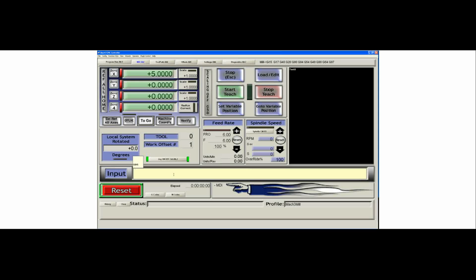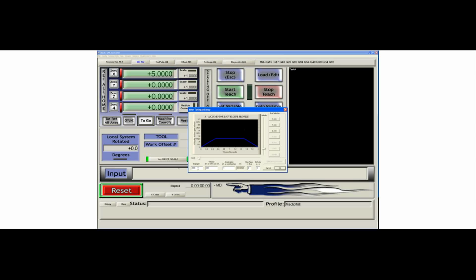This is all set up by the motor tuning steps per inch. If we go up here and bring up motor tuning, you can see that for each axis there is a steps per. This needs to be set to the number of steps the system needs to send out to move your axes 1 millimeter or 1 inch, depending on the selection that you have selected for the system. The acceleration and the velocity you should set to a comfortable level prior to doing anything, and hit Save Axes for each axis. You can then adjust your steps per inch to make the system accurate.